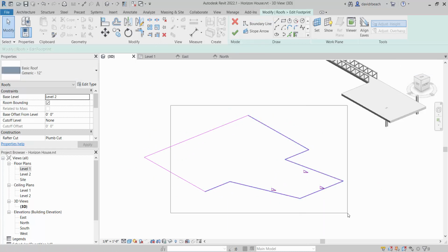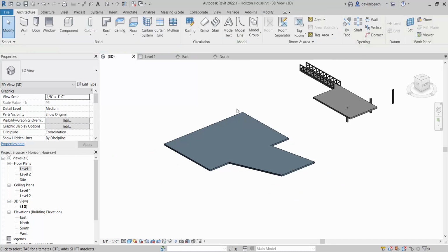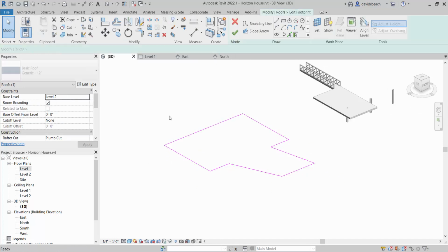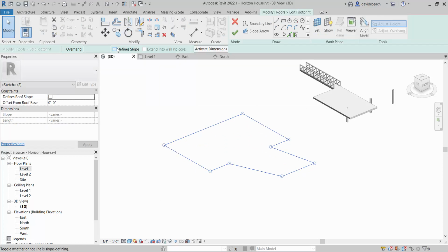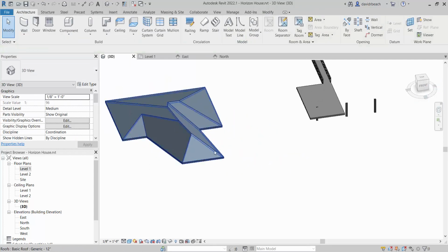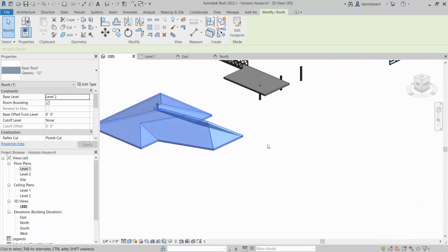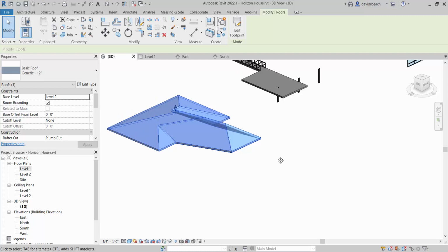So it behaves exactly like Revit always does. Nothing is sloping. Everything's flat. As long as that's what I'm telling it to do. If I come in and tell this, edit footprint, that I want everything sloping, it's going to create a terrible mess. It's officially a weird roof, but it's capable of forming it, which is kind of cool. Yeah, question? Oh, that was your question.